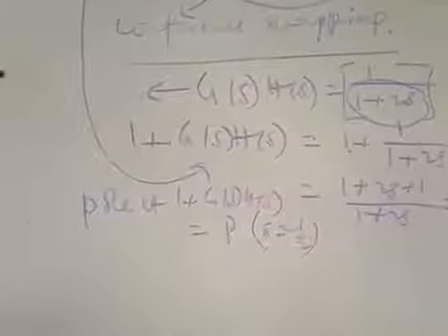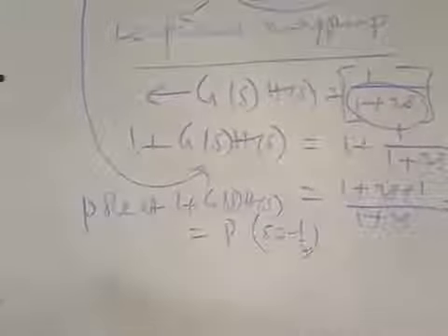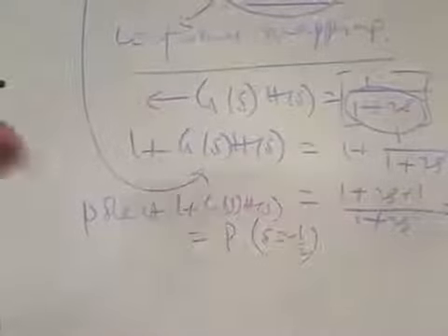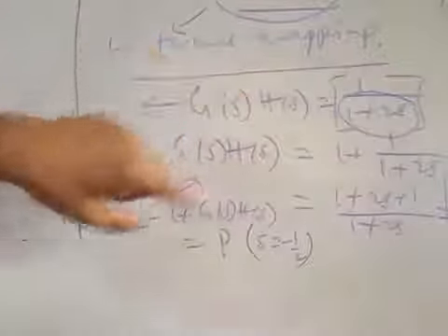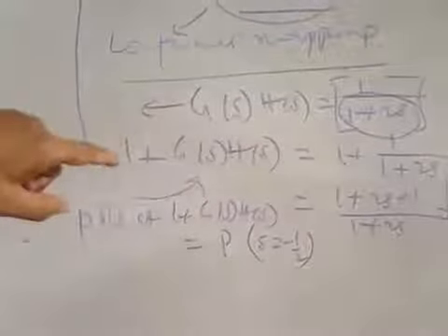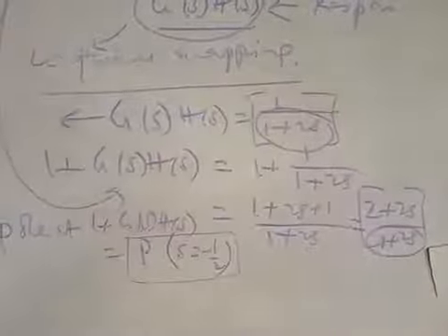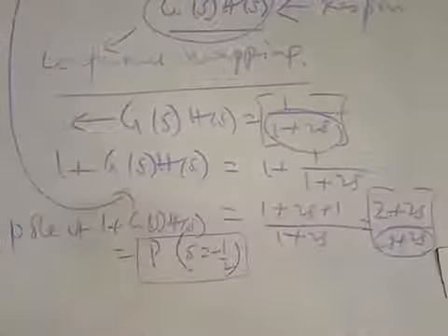What is the conclusion out of this? The number of poles of the open loop system is the same, with the same position, as the number of poles of the closed loop system. So there is no confusion regarding this, and from the open loop transfer function you can get the total number of poles of the closed loop system.